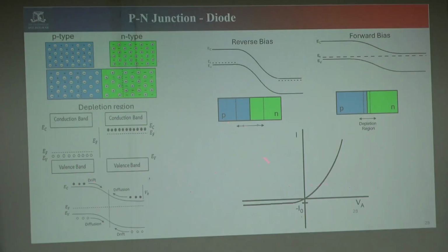Okay, when you have the positive bias and the charge exceeds this junction potential, it will start conducting. But if you have the negative bias, it won't conduct at all. This is the basic principle of how a diode works actually. It only conducts in the positive bias. A diode is a one-way traffic. It conducts charge in one way only. The other way it doesn't conduct.